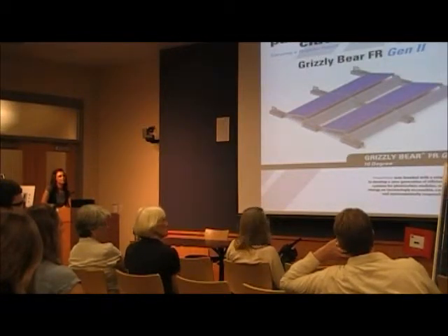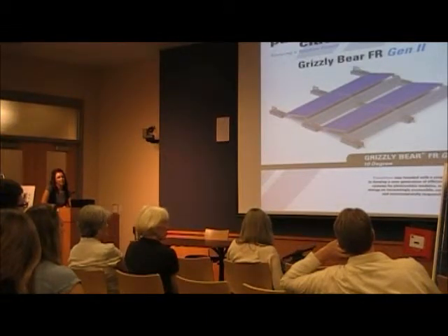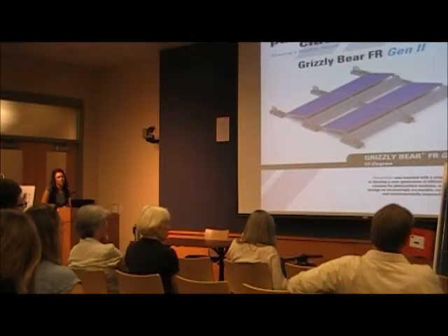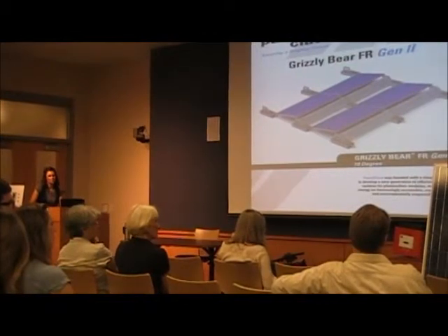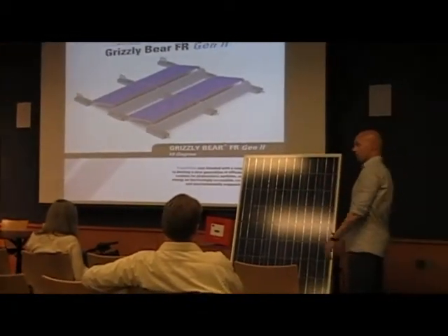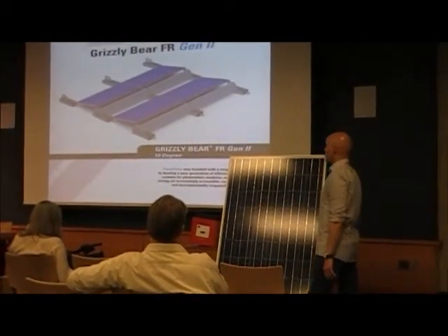You don't want to, like, this thing's making you money every day. So if you take it off and it sits for 3 weeks, it's not making you any money. So when you look at an application, you've got to figure out what your risks are, what's involved, you know, roof orientation, and other aspects involved when you're looking at rooftops. Because we haven't been designing our buildings to install solar. You've got venting, you've got HVAC units, you've got big parapets, you've got all these things up there, and on retrofits, it makes it very challenging.